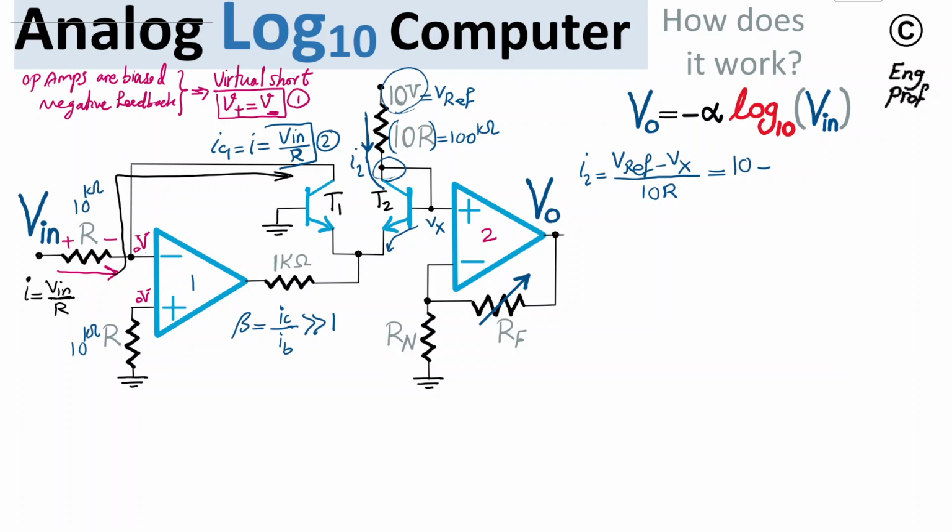The Vx, I have a quick comment about it, practically compared to 10 volt. So VBE of a transistor during nominal operation is on the order of 0.6 to 0.8, nominal 0.7, hardly getting to 0.8. So that's the range. The same thing applies to this one as well, between 0.6 to 0.8. So let's say this T1 is roughly 0.7, and this one is nominal 0.7 as well. So with the variation expected, this Vx at the base of transistor 2 is not going to change by more than plus minus, say, 0.1 volt or so.